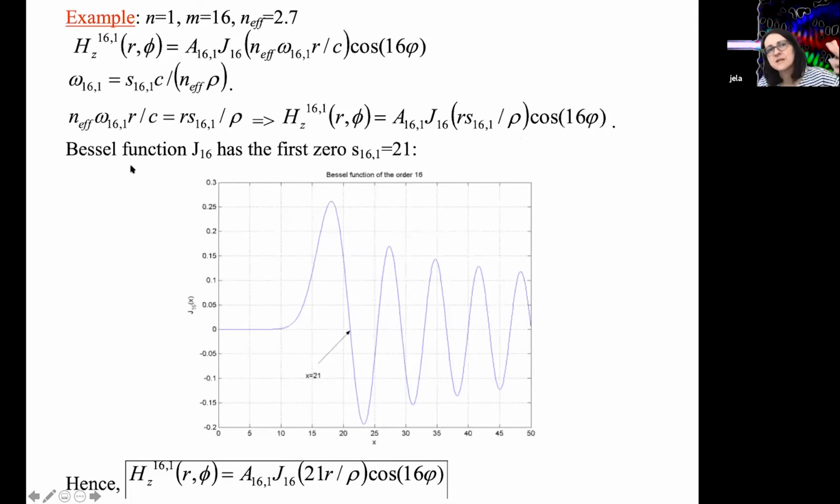I mean, frequency is fixed because of the wavelength that is fixed, but in this case, when you are designing the diameter of the disk, it would change the diameter of the disk relative to the wavelength of 1550 nanometers, which is your target wavelength, right? So for the 16.2 mode, you would truncate it here at the second zero. That would give you a very different radius of the disk if you would like to specifically operate at 1550 nanometers. But it would also mean that as you're going in the radial direction of your microdisk, you are going to see two lobes of the field, right? There would be the first ring, first lobe, and then the second ring.